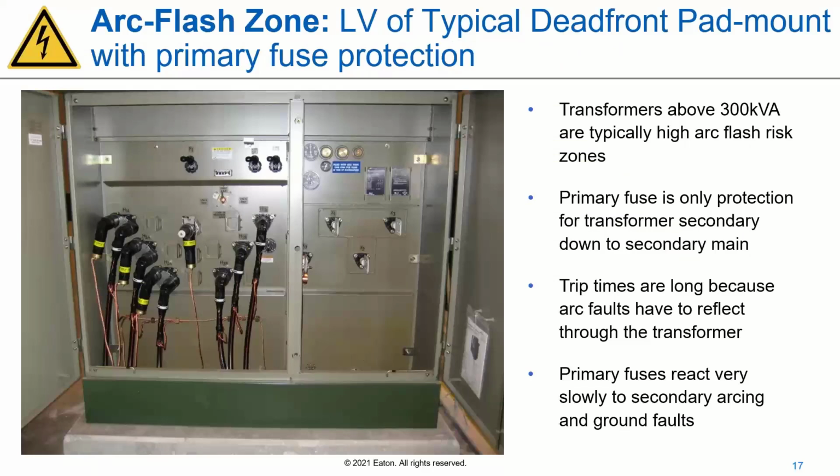So we're looking at the front plate with the high voltage and low voltage compartment doors open. It is very common to have accessories located in these compartments. So you have your nameplate over there with all the transformer information, the KVA, the voltages, the part numbers, things like that, along with your gauges right next to it, things like your temperature gauge, pressure vacuum gauge, liquid level, things that you might commonly go and check on for maintenance.